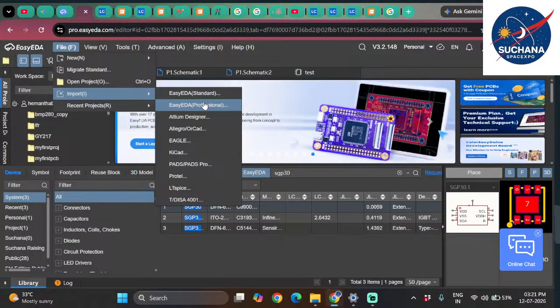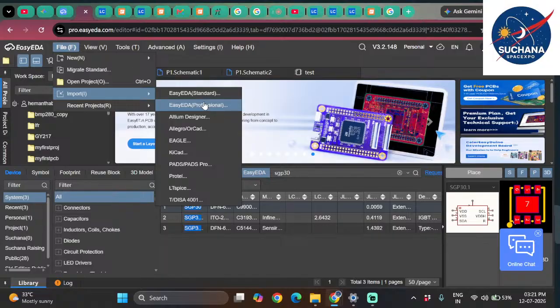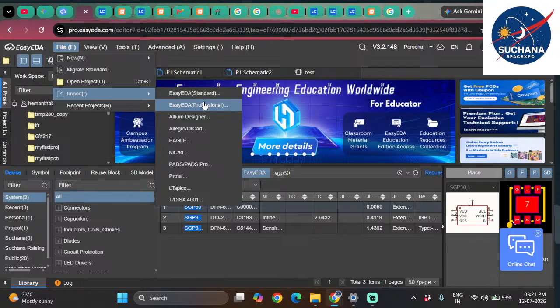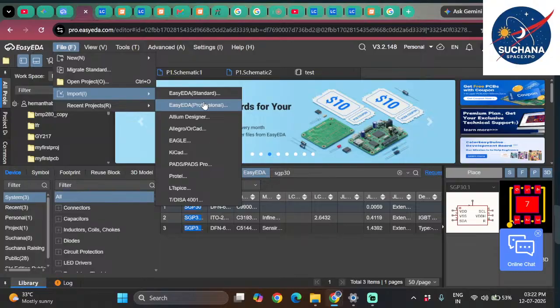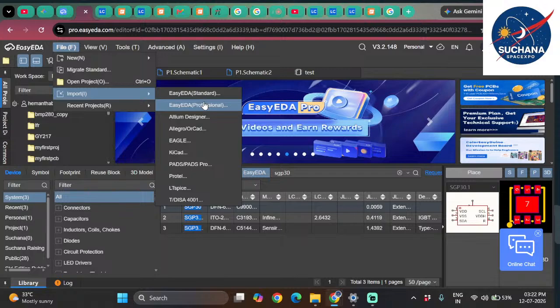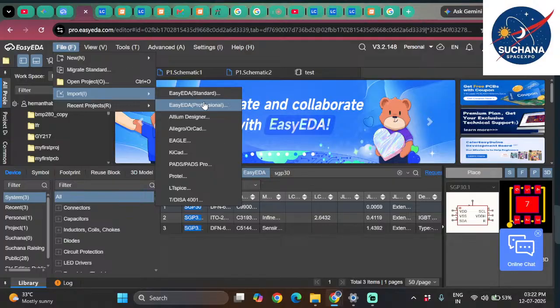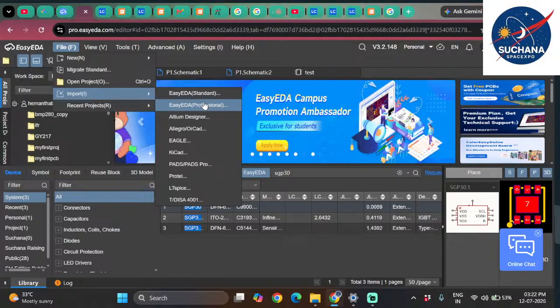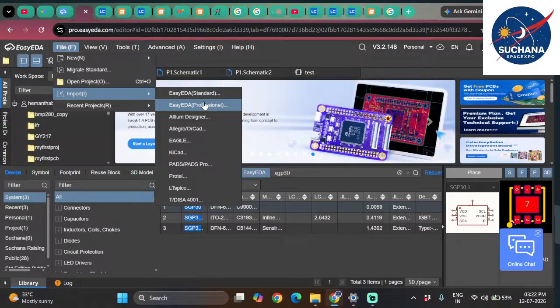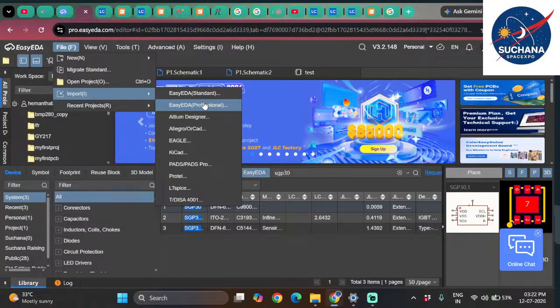Then we discussed the characteristic impedance formula, where we revealed that not only the width plays an important role in the efficiency and signal transmission in the PCB, but also the height of the laminate material we are using, FR4. The height of the laminate material also plays an important role because it affects the overall characteristic impedance, which decides the speed of the transmission of data in PCB. Similarly, we discussed many things, like environmental safety, consumer safety, polybrominated biphenyls, polybrominated diphenyl ethers, and endocrine disrupting chemicals. The chemistry behind that, RoHS, restriction of hazardous substances, 10 different chemicals which are banned in the European Union in the manufacturing of PCBs.